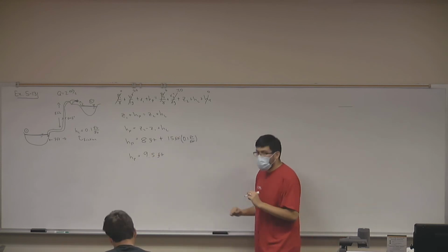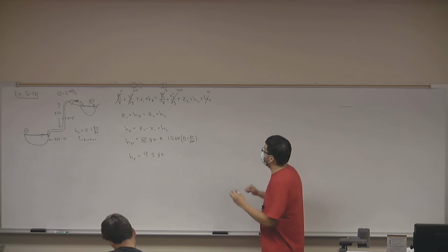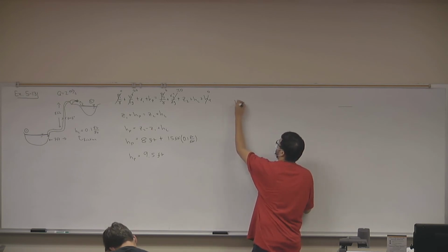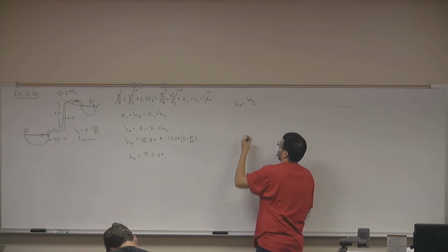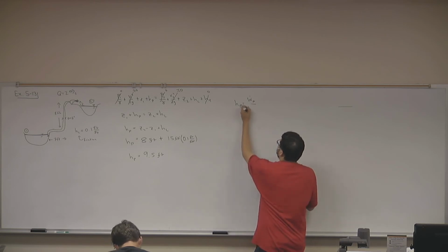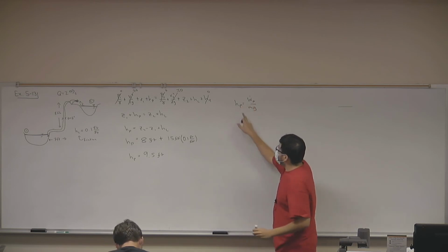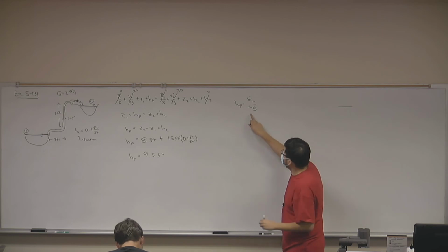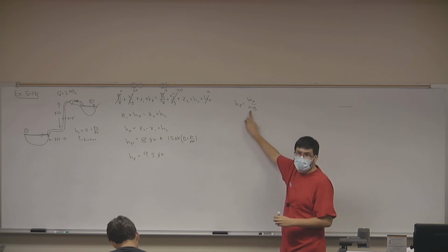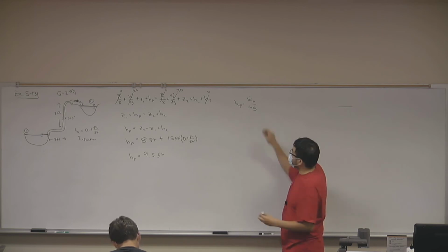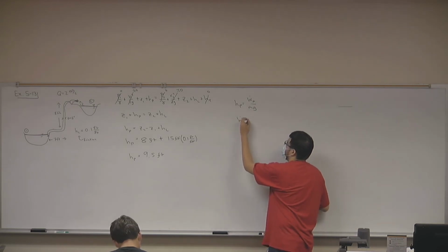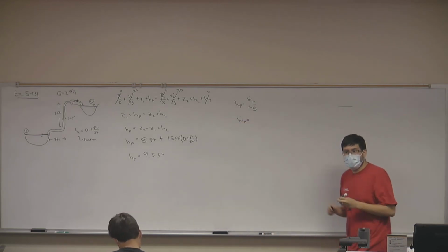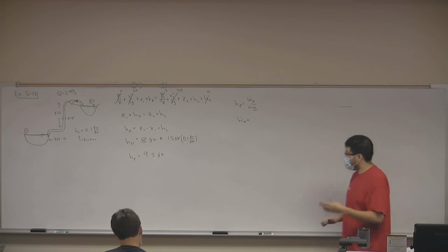But how do we go from pump head to horsepower? Remember that pump head was equal to the pump power, so horsepower, divided by mass flux times gravity. Do you have pump head? Yes. You have flow rate, so can you calculate this mass flux if you have the flow rate? And you have gravity? So you can go ahead and solve for horsepower, and I will let you take care of that yourself. Okay? I'll see you next week.